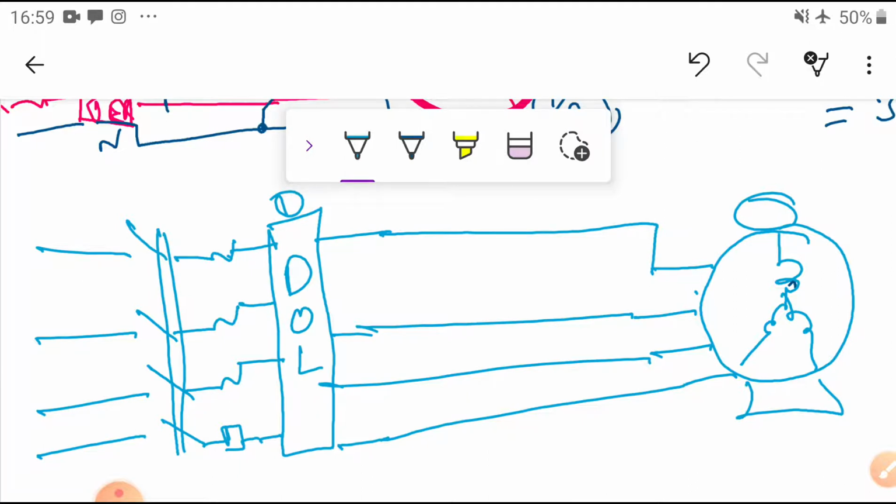Now in this case I am going to connect the 3 wattmeters method. Here you are assuming this motor's R phase winding, Y phase winding and B phase winding may not be exactly equal. That means the impedance of R phase, Y phase and B phase are different values. Impedance Z is equal to R plus jX, the resistance and leakage reactance of each phase.